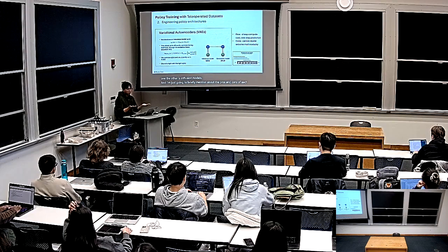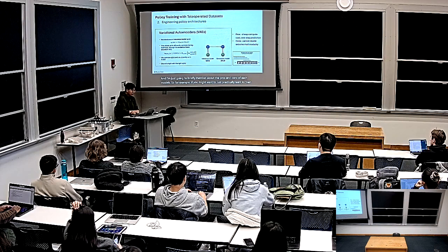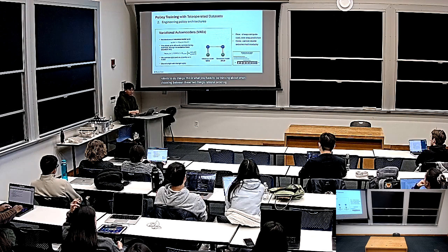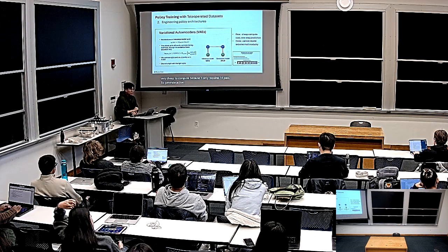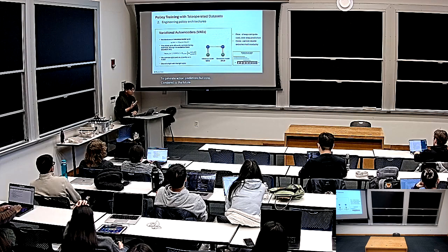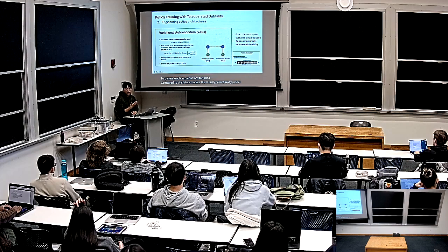So if you practically want to train robots to do things, this is what you have to be thinking about when choosing between these two. Variational autoencoders are very, very cheap to compute because they only require one forward pass to generate action predictions. But the con, compared to diffusion models, is that they cannot model extreme multimodality.